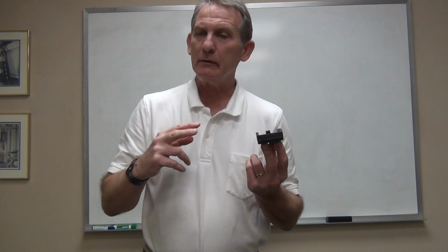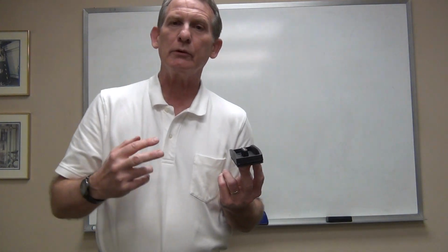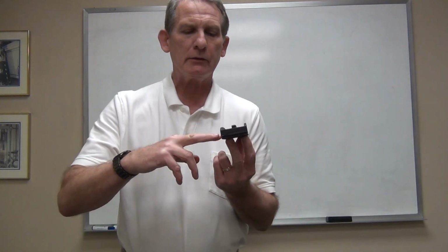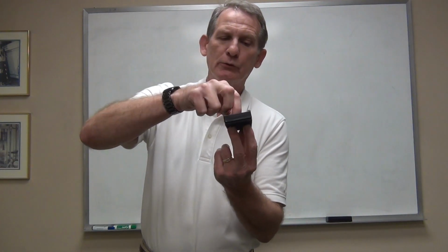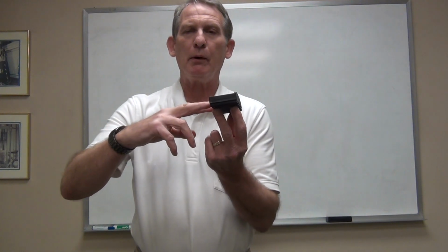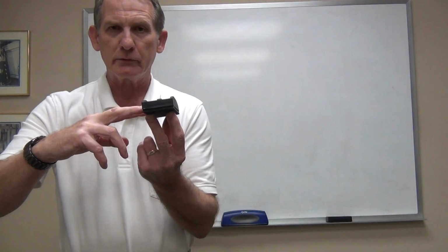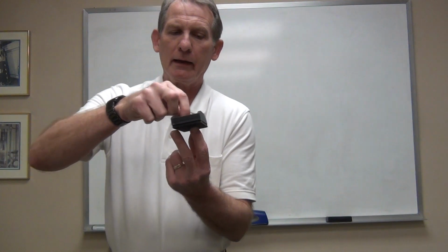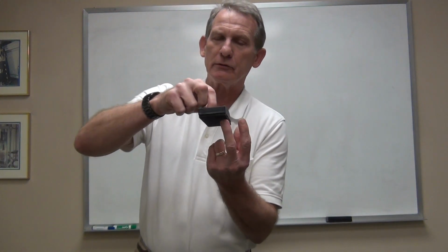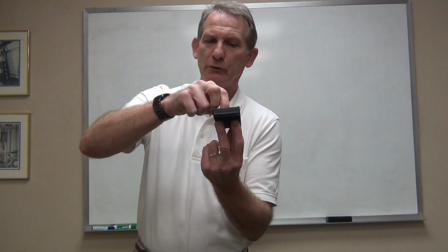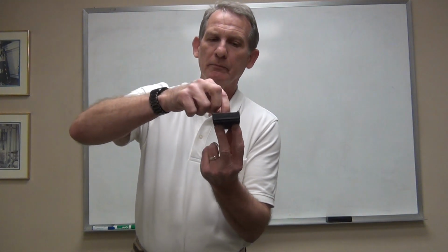I can add additional contact points or additional datums. Let's say I force 2 points here and say this part must now sit on these 3 points and it must bump up against these 2 points. At that point I have constrained this translational degree of freedom, but not this one.